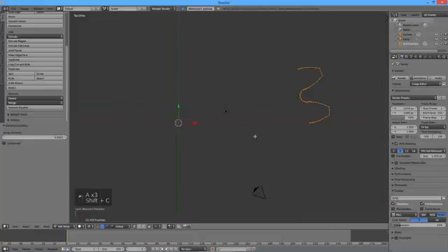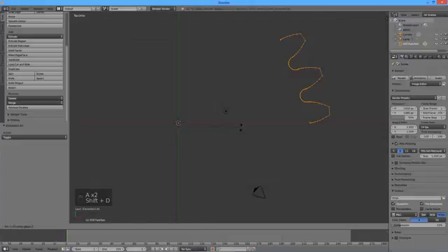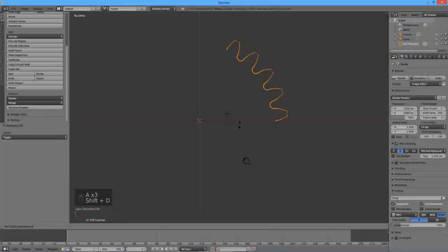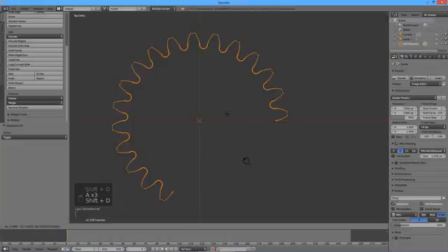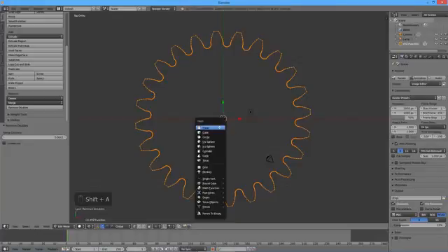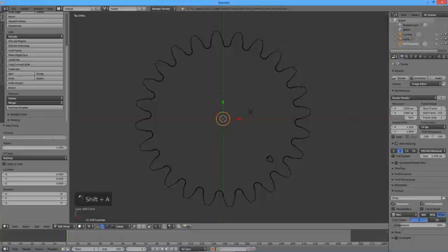Press Shift C to return the 3D cursor to the default position. Press Shift D to duplicate, then R to rotate, then Z, then 15, then enter. Repeat with the rotation angles of 30, 60, 120, and so on until the entire outline is completed. Select everything and press Remove Doubles. From the information window at the top, note the number of vertices in our object, 888. Add a circle by pressing Shift A, then Circle. Enter 888 for vertices, and 10 for radius.